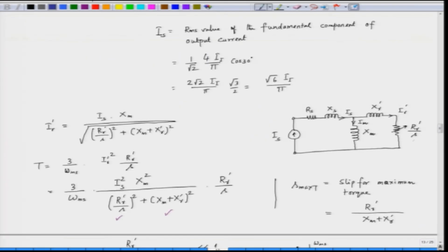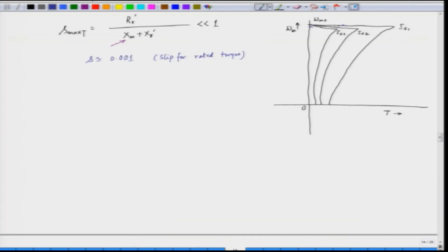Now, if you see the equivalent circuit, when slip is very, very small, the slip resistance is very large. So, since the resistance becomes large, current predominantly flows through the magnetizing reactance. So, this leads to saturation of the induction machine. So, at this point, although we operate at the rated torque here, the machine is heavily under saturation.